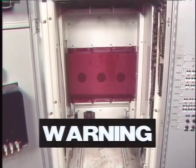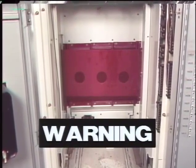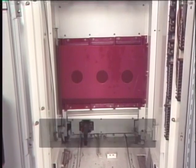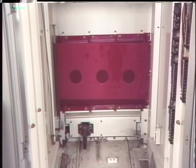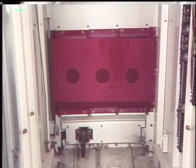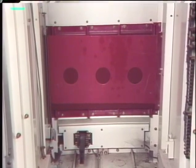A general warning is needed here. Before starting work inside the cabinet, make sure that the control power circuit is de-energized. In addition, even though the breaker has been removed and the control circuit has been de-energized, the bus and line connections inside the cabinet may still be energized.